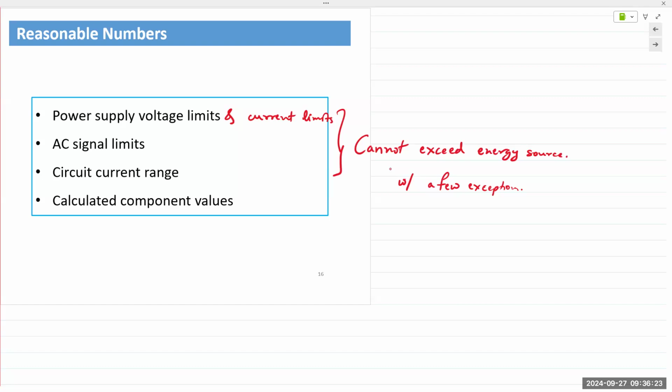That's something we'll look at in chapter 3. It's called a clamper circuit. That's also used in function generators to apply DC offset to your AC signals. You'll remember some experiments where you apply a DC component known as a DC offset in your function generators. That requires a clamper circuit because it clamps your AC signal at a positive DC value or a negative DC value. Okay, so in those kinds of circuits, it is possible to obtain larger voltages and currents. Any questions?